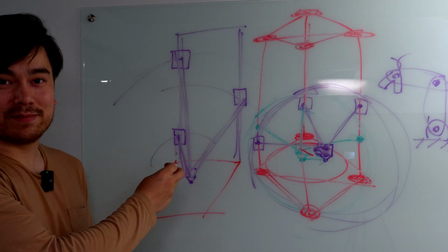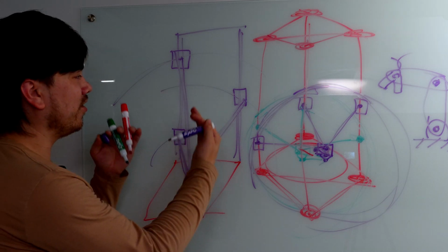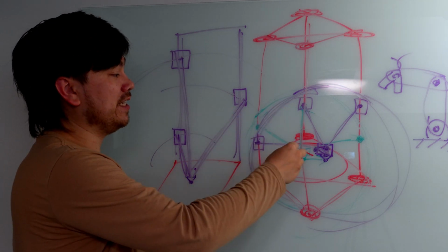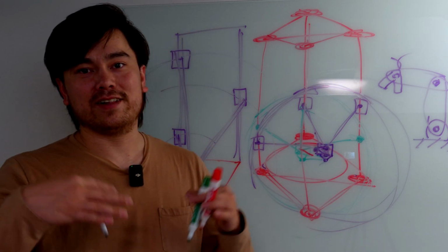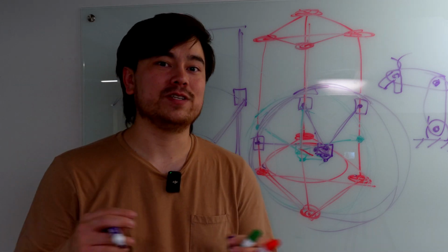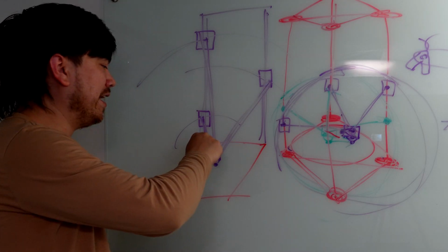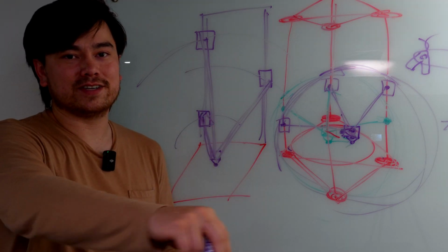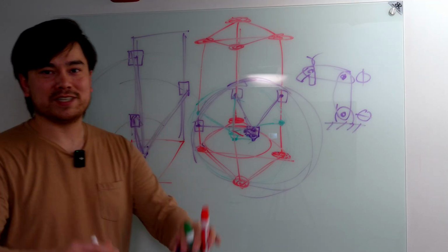So you could make a delta printer that just had 2 rails and had all of the axes behind the print bed. But the reason why they'll usually position them equilaterally around the printer is because it makes the math easier and all of the sub-assemblies are identical, and that ends up usually being the stiffest when you equally space things out. When you do something like this, having the end effector way out front outside of the middle point of these little things, it basically makes it harder to control that point precisely. There's all sorts of studies and trade-offs that you can do with this stuff, but yeah, I'm seriously going to stop now.